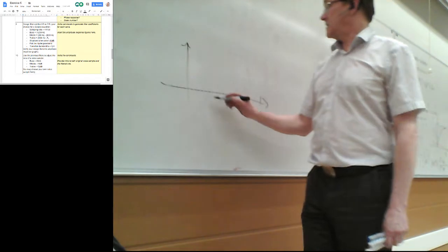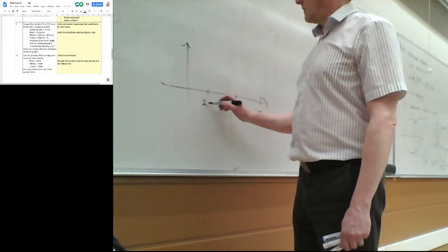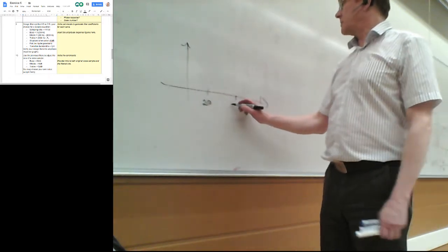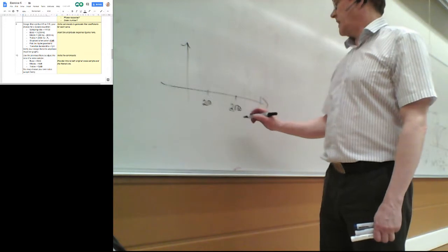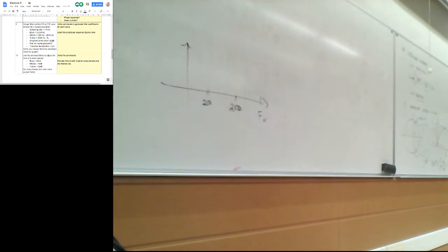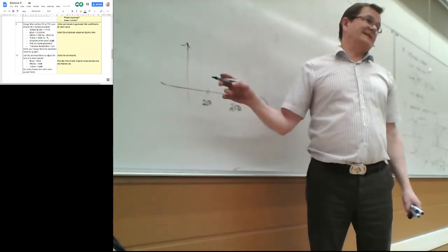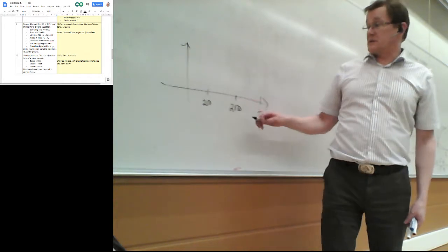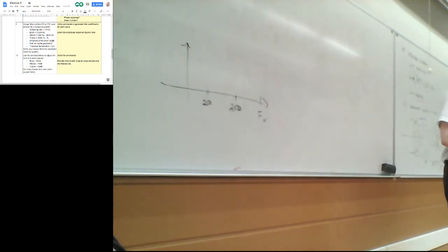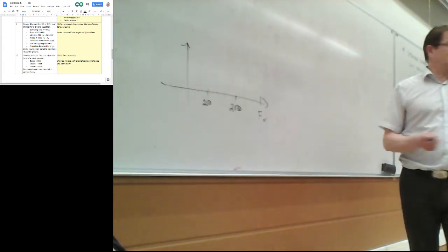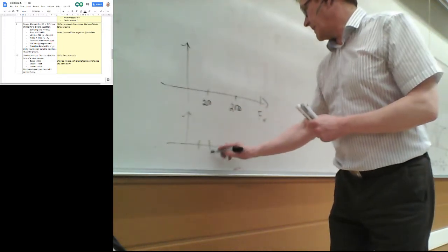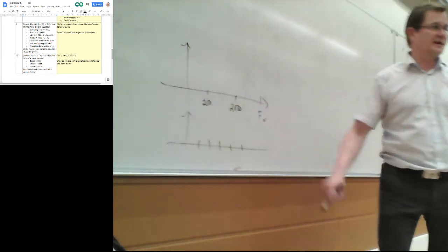Nyquist frequency. Low frequencies are actually from 0 to 200 Hertz. Then the mid frequencies are from 200 Hertz to 2 kilohertz. Then the high band would be from 2 kilohertz beyond. On digital filters, for historical reasons, the frequency scale is linear. But as you remember well from the analog systems, that's not the natural way. The natural way is the logarithmic frequency scale.